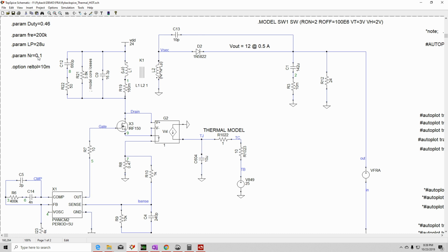So remember, the current will be power, resistance is still resistance, and voltage is temperature in Celsius. Okay, so keep that in mind. So this will represent the power. Okay, it's a current, but remember that it's representing in the mechanical world the power. But which power? Well, it's calculating the power of the IRF150.